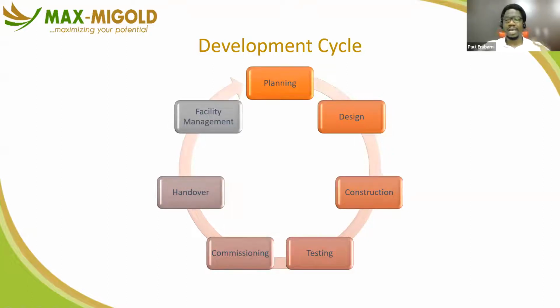What goes into construction? A contract package that includes the bill of quantities and all of these design drawings. In construction, you start doing another round of drawings. We call these construction drawings. So you are trying to have specific work methods, specific jointing, specific instructions implemented in drawings that the actual builders can understand and relate to. Blow-ups or blowouts show a zoom in. We call those details, made at the construction stage, so that the builders know exactly what they are building.